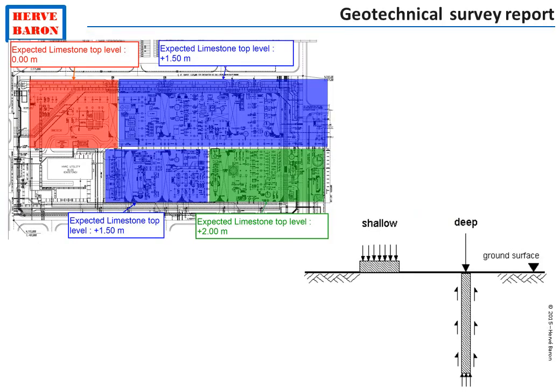The soil investigations also result in the issue of the Geotechnical survey report. It contains the design basis for foundations, whether these foundations shall be shallow foundations or deep foundations. What is the soil bearing capacity? And this allows civil to start with the next activity, which is the design of equipment foundations.